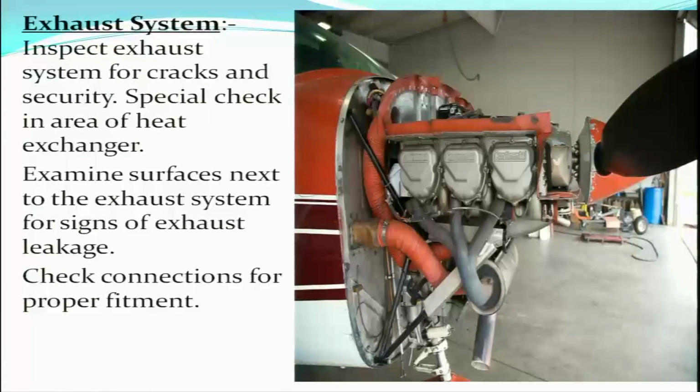Coming to the exhaust system. Inspect exhaust system for cracks and security. Here is your exhaust system, you can see in the figure, this is your exhaust system. These are the exhaust coming from each cylinder. This exhaust system is to be inspected for any cracks and security.